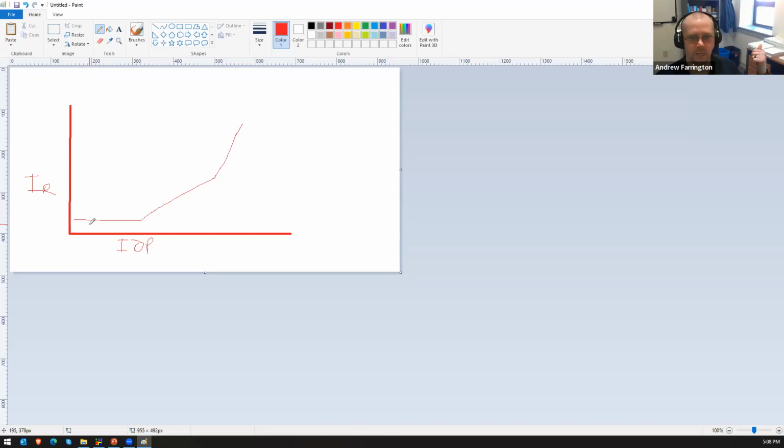In the linear region, or in the slope 1 region, you're looking to compensate for the inaccuracies that are not transient. And what I mean by that is, you can have the load tap changer change, right? So you're going to have some inherent inaccuracy in there. If you set your transformer taps to the selected no-load tap changer position, LTC neutral, everything should be, you know, 0 operate current.